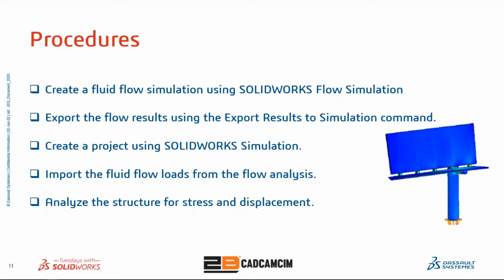To import loads from a flow study into a simulation study, it must be pointed to the FLD file, as we will see in the next case study. The FLD file holds the flow results that will become a boundary condition in the SolidWorks Simulation study.